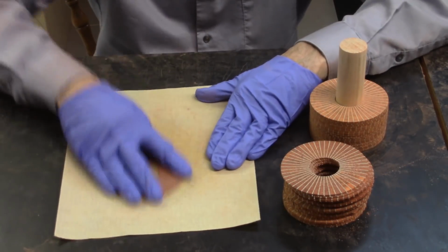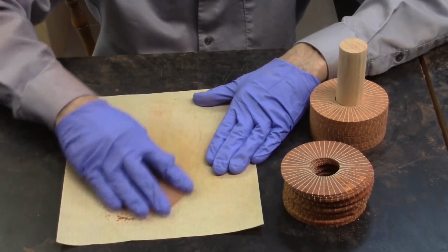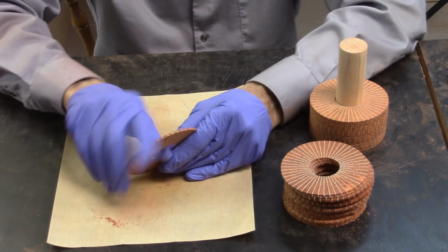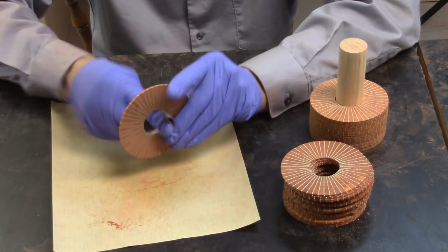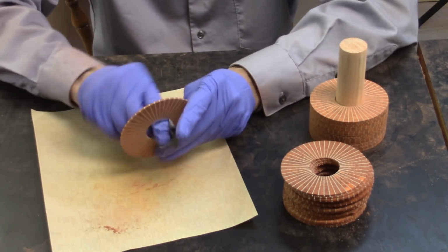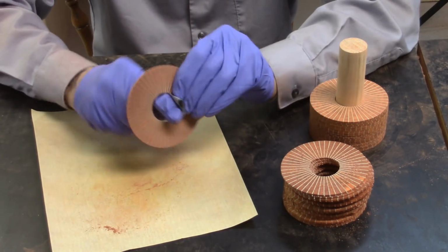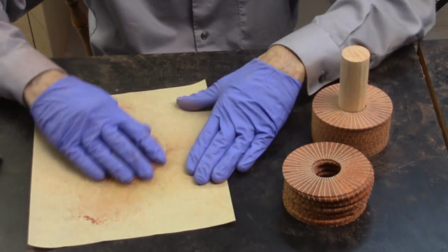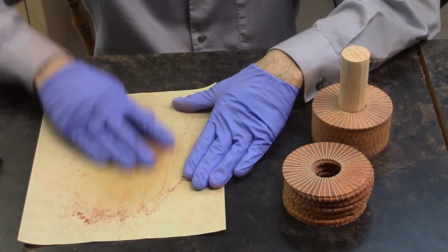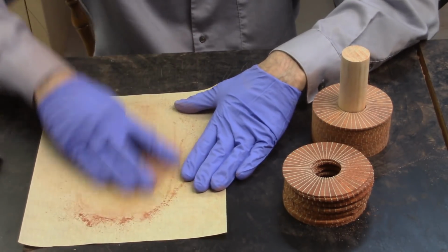Before the sliced disc can be glued together, the fuzzies and burrs must be removed from the disc. A quick sanding of the flat disc surfaces and the disc edges with 220 grit sandpaper is all that is required for this cleanup. After the discs have been cleaned up, I mount them on a wood dowel so that I can be sure they will mount on the wood glue-up jig, and also to plan for the final glue-up of the assembly.